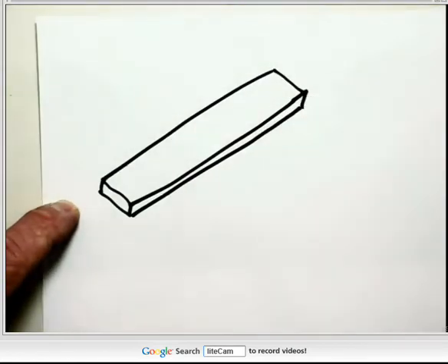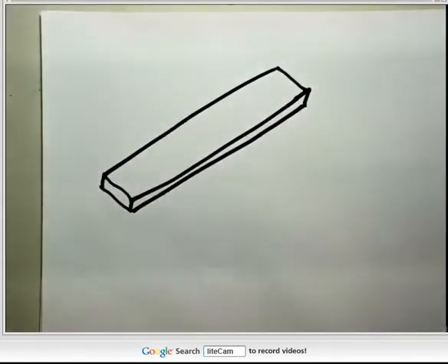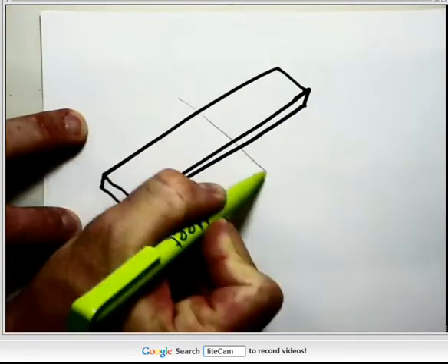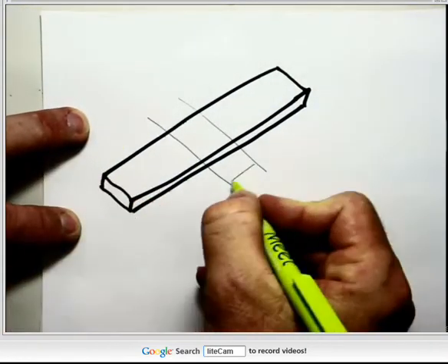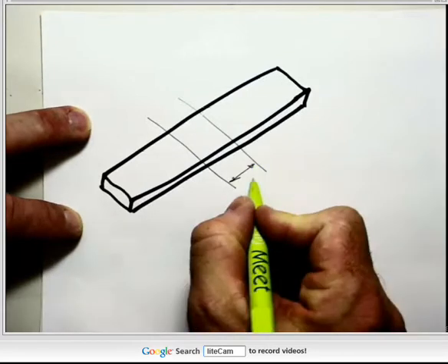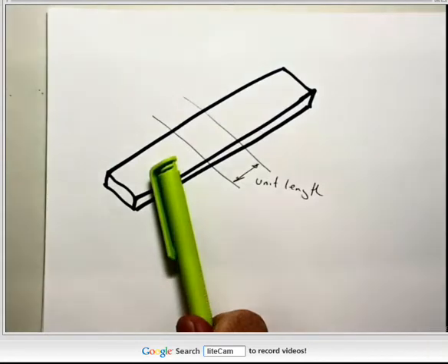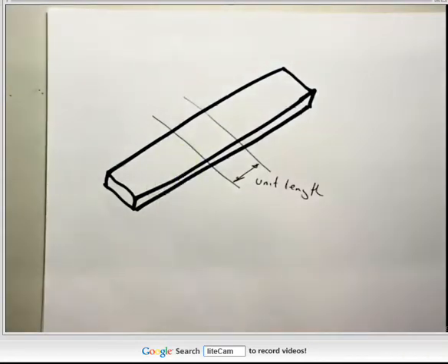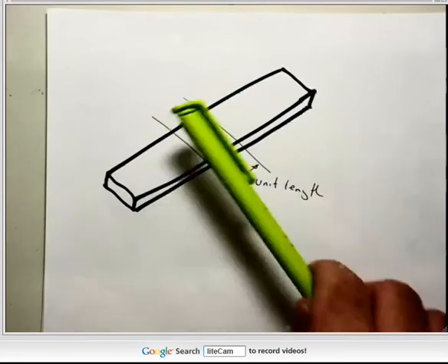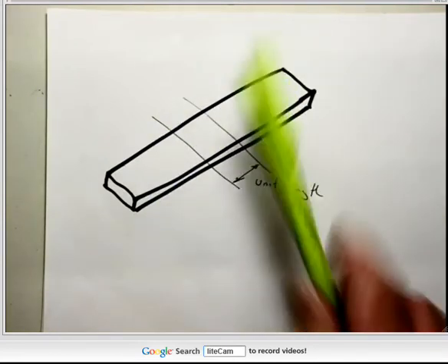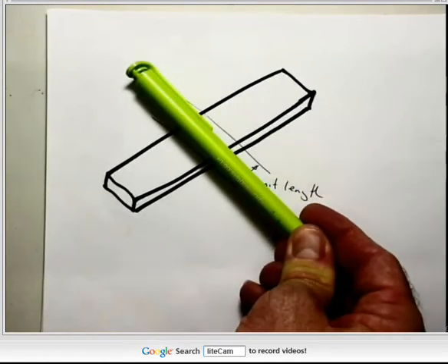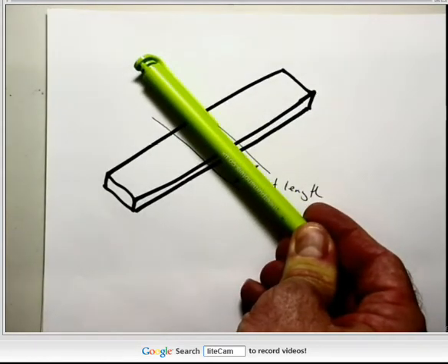So in analysis, what we do is we go to the middle of that footing, and we consider a section of it of unit length, and because we've got footing alongside it which is identical to what's in our unit length on both sides, the deformation occurs only along that axis.